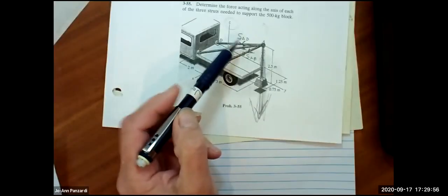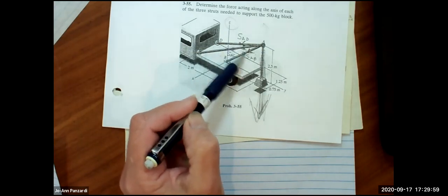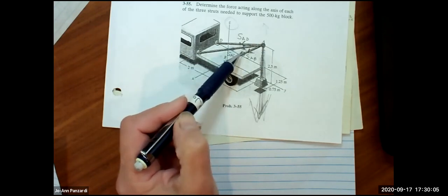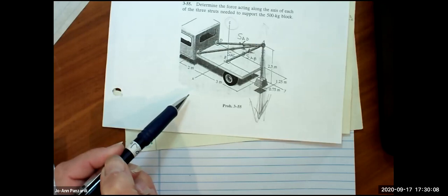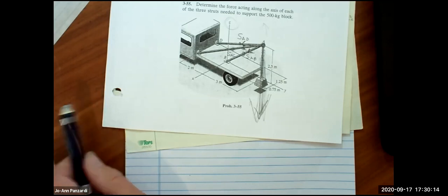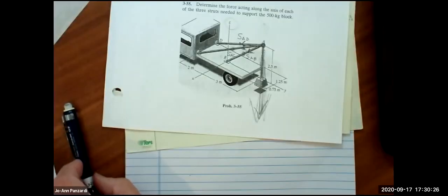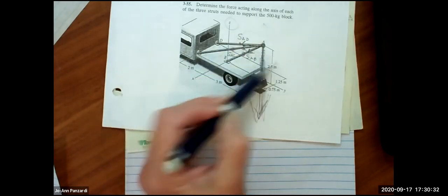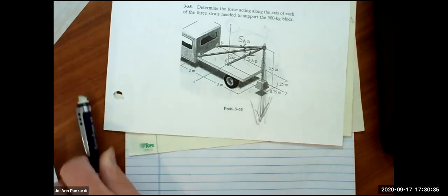They're not all going to be the same. I'm trying to get you into the sign convention of drawing things that you don't know which way they're going: draw them so that you're drawing them in tension. And then if you get an answer in negative, you know it's compression and it's actually going in the other direction. Okay, I got it. All three struts, in my head, were all doing the same thing, but I guess we're going to find out that maybe they're not. They can't, because like you said, there's no way for all three of these to be pushing down. Otherwise, this whole thing is going to just slam on the bracket.